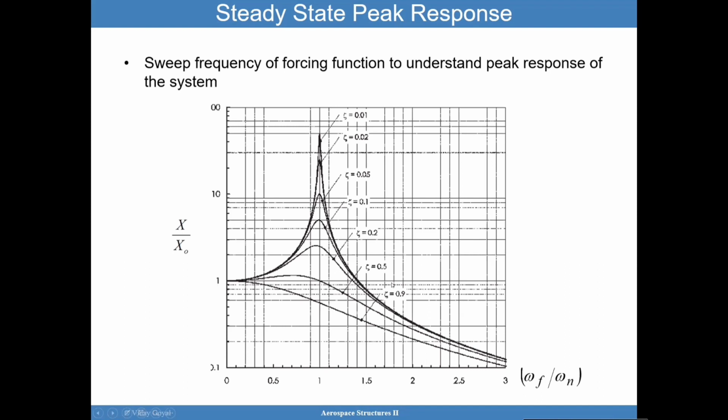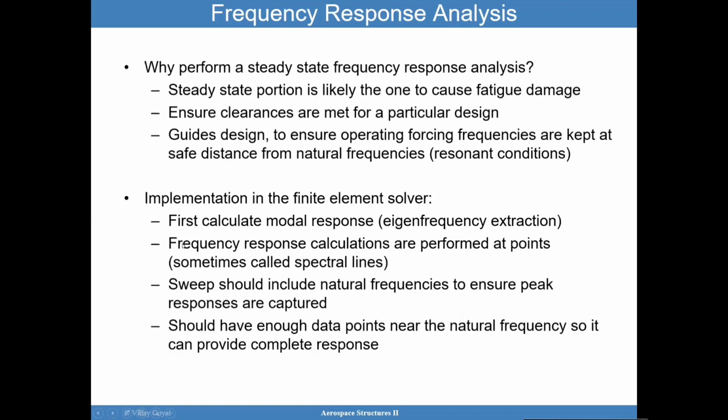When you move away, which means omega f is much greater than omega n, you're vibrating the system like crazy, but the natural frequency of the system is perhaps 3 hertz, and omega f could be 100 hertz. Perhaps you're not really doing much by putting in that input. And so that's shown here: you're getting a very small amount of response compared to if you were to apply it statically. And performing a steady state frequency response analysis is helpful for evaluating fatigue.